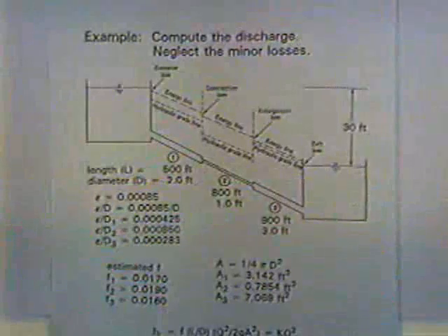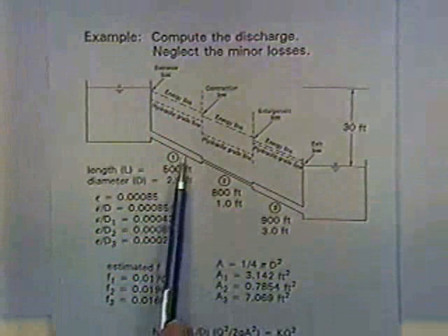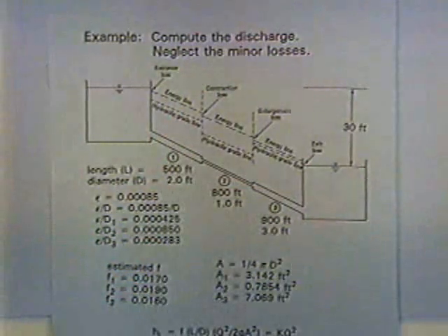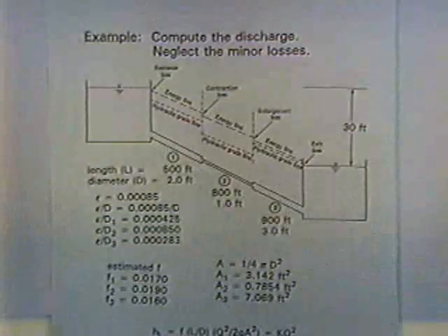Now we're just taking the basic concepts that are expressed on those 2 pages of the notes and working some problems with them. And so here's the same problem as before, or a similar problem, where we're connecting that reservoir that has a 30-foot difference in water surface elevation. The only difference is that it's being connected by 3 pipes in series. And so the problem is to compute the discharge through the pipes.